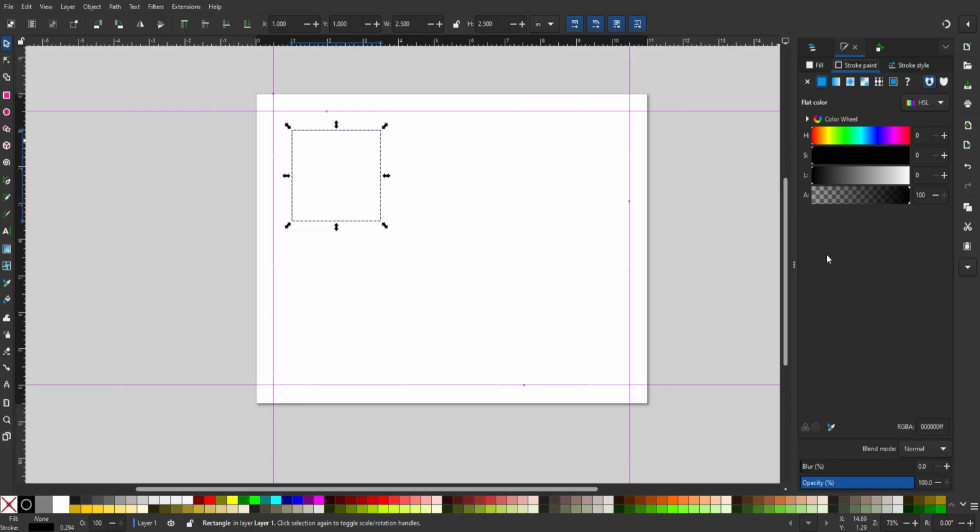So for the laser cutter, it doesn't really matter what color the stroke is, but typically you're just going to leave it black. It's going to be following the path, and it's not going to be considering color information. Really, anything I make for the laser cutter, I tend to do in black and white because it doesn't read color information. It only reads, is this an object to etch, or is this a line to follow and cut?